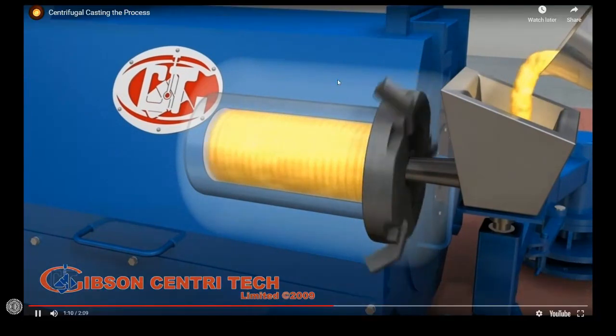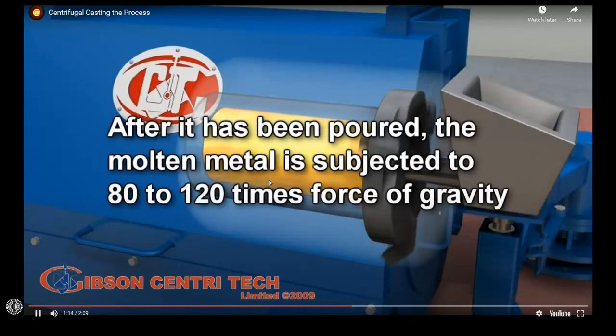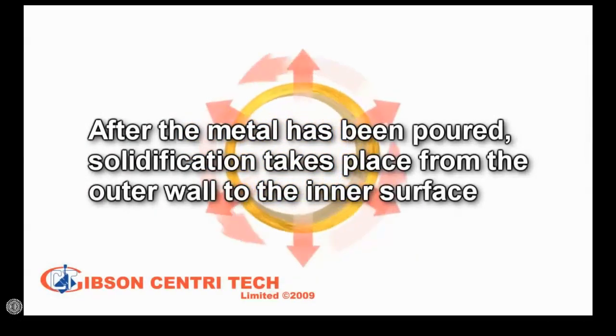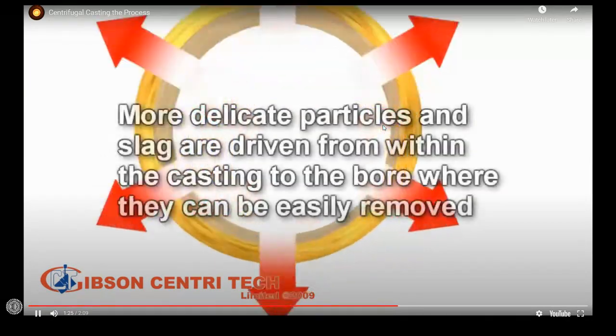Metal goes in as your mold is spinning. So the molten metal is subjected to 80 to 120 times the force of gravity. That's that centrifugal force we are talking about. Solidification is going to take place from the outer wall to the inner wall.